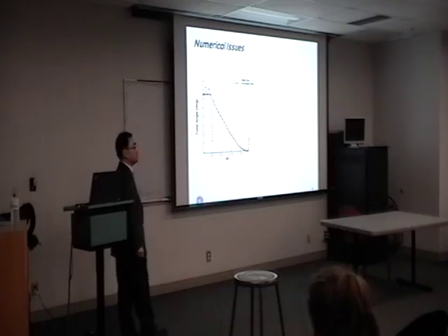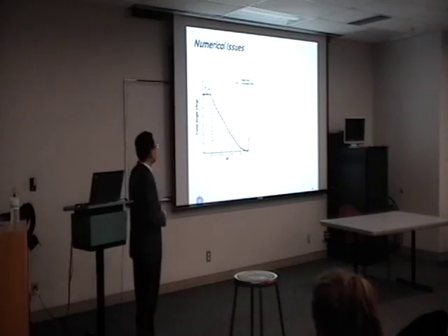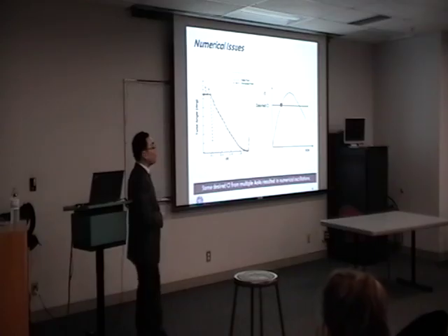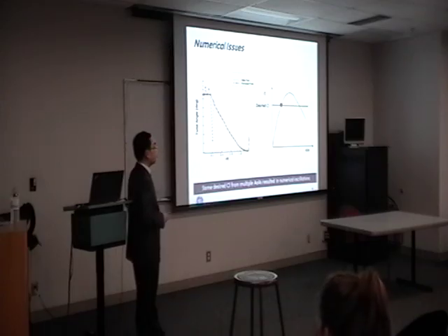I investigated this problem and identified that it is associated with flow separation. Whenever flow separates on the blade, the CL, the lift coefficient, behaves like this: there is a linear region with an increase in CL as a function of angle of attack, and then it decreases because of the flow separation.